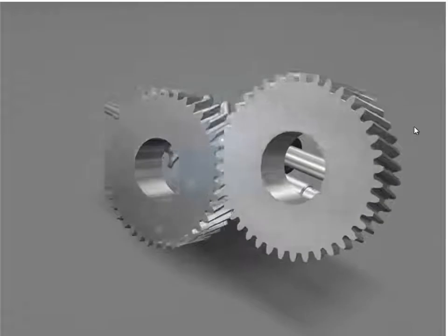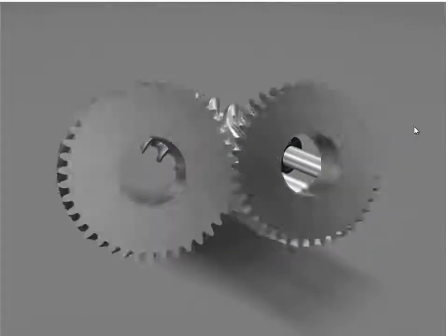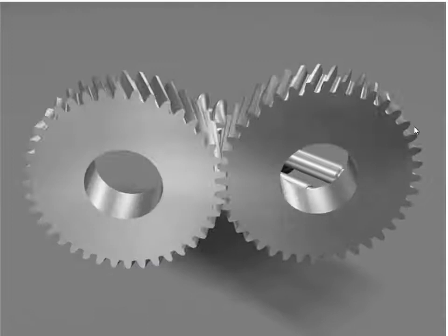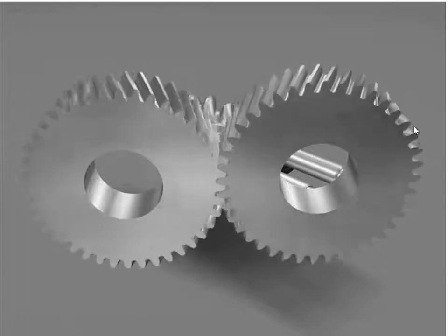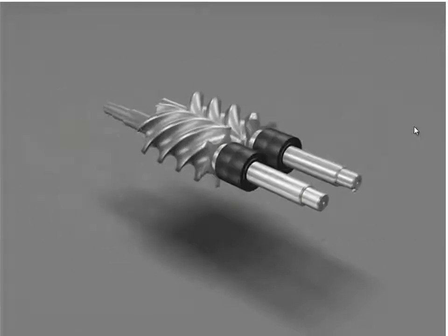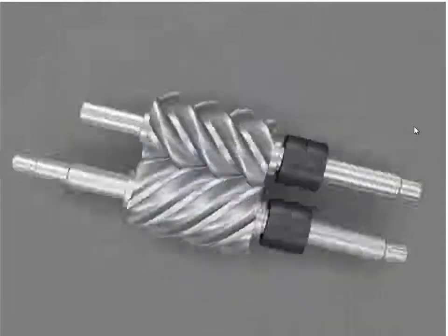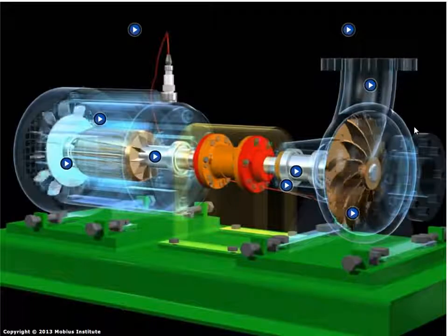Same goes with gears, whether they're timing gears or inside a gearbox. Are they aligned? Are they lubricated? Is there damage to the teeth? Anywhere? Whatever the case may be. Vibration analysis lets us look inside the machine.